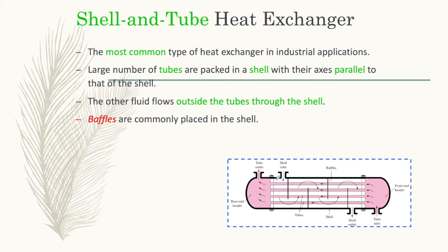So as we can see here, the flow of the fluids will be longer than when we have one big shell, and without baffles we will only have reduced contact time for the fluid with the tubes.